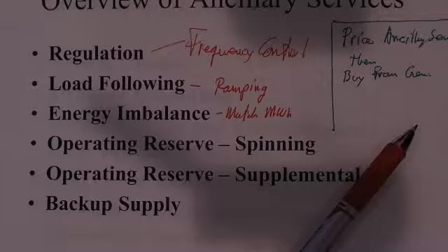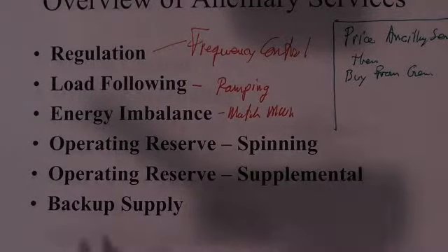So somebody has to operate below their max, and that difference is the spinning reserve. If the unit is on and it's synchronized, it's spinning, and the difference between that amount and the maximum for that generator is called spinning reserve. Again, it's a service, and you could have a big generator that says, "I'm not going to do that." Well, maybe it has to buy its way. Maybe it has to say, "Look, I'll pay you so that I don't have to participate." That's legitimate.